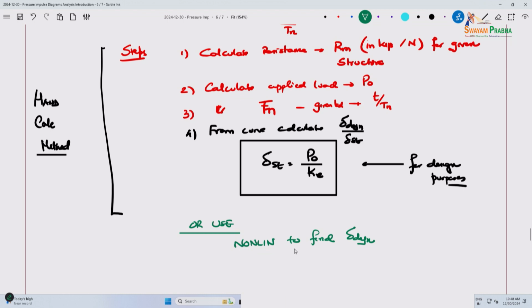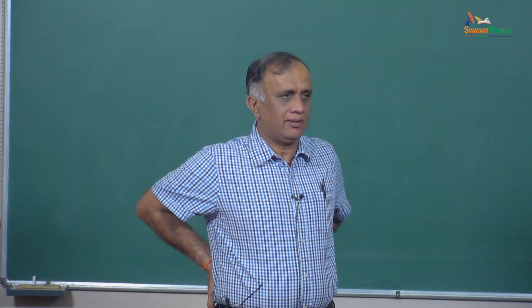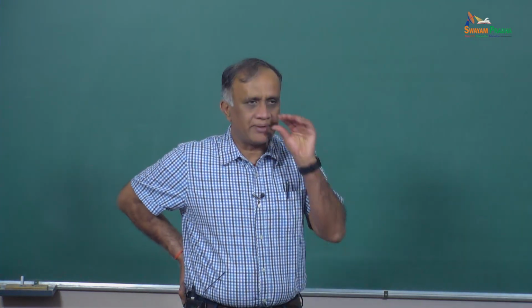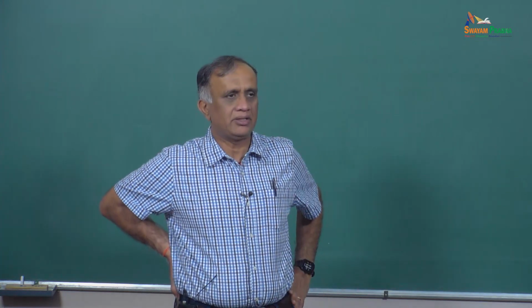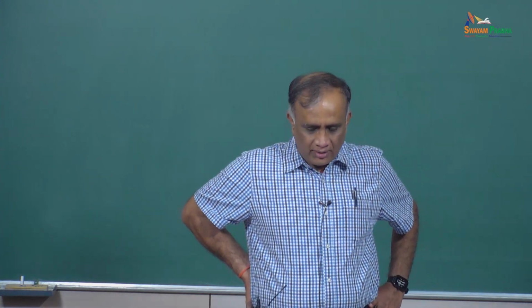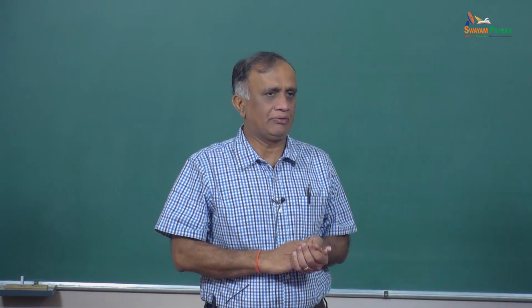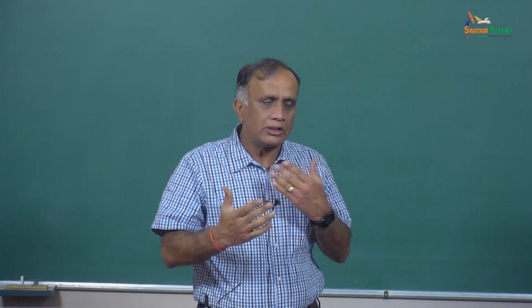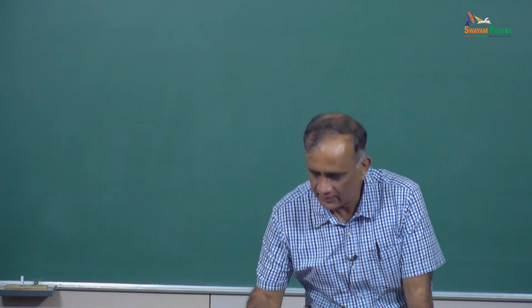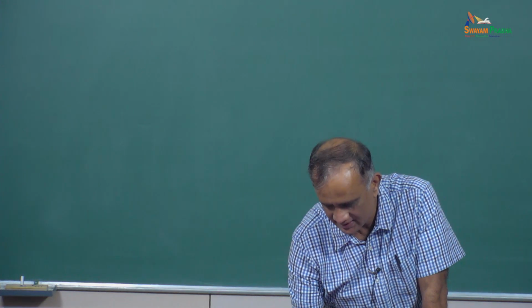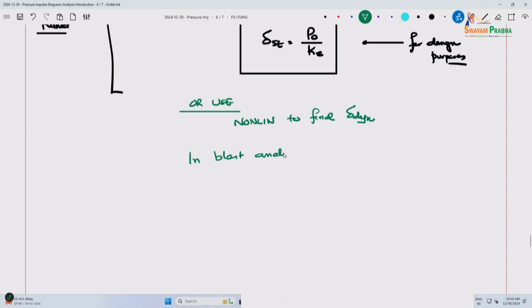You might ask, why are we doing both again? Remember how conservative SDOF is, right? SDOF can be quite conservative in estimating, as you have seen in the paper that I showed you. So until you get an idea of how conservative it is and how to use it, it's always good to compare with two different methods in such uncertain blast analysis or design.